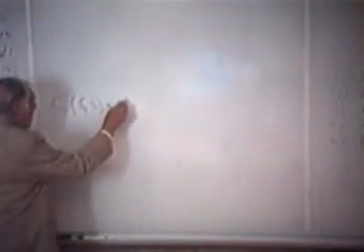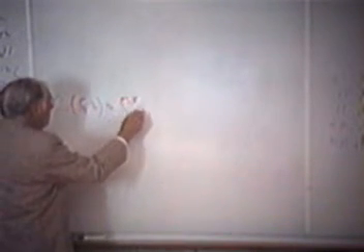C(5,2) is 5 times 4 over 2, which is 10. The 10 decimal symbols were represented in a telephone company by 2 relays out of 5 being up, or sometimes 3 out of 5, depending which code they wanted. You recognize the 2 out of 5 and 3 out of 5 codes are really the same thing. It's a question whether you have them up or down. And you can see that if one relay fails, or one relay closes when it shouldn't, there'll be an odd number of relays.